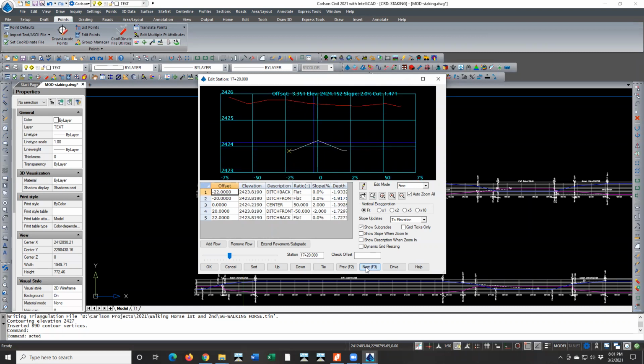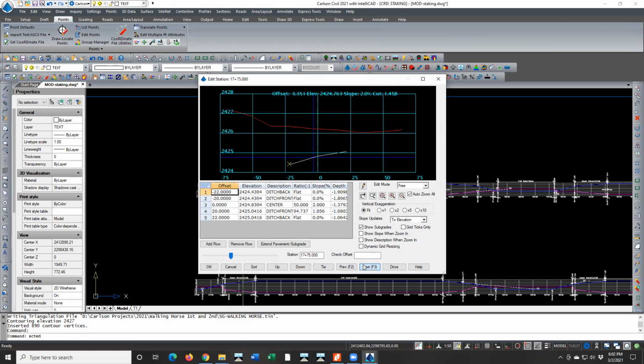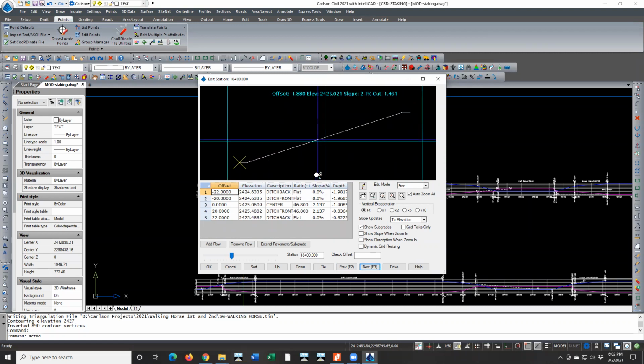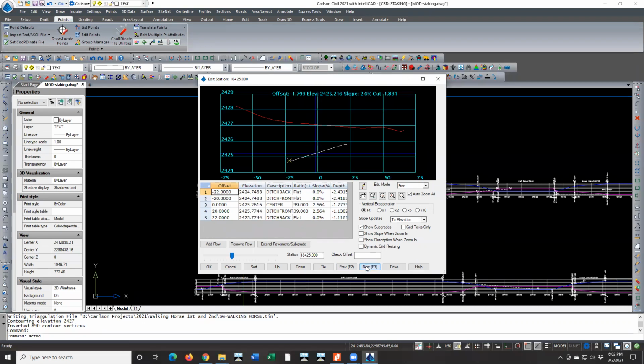That looks better. And everything's holding. So I'm wondering how the super elevation diagram will look now. So now see, it's all holding that 2%. Now, this is now in full elevation. Is it? No, maybe not quite. Should be like 19 plus 60 or something. Yeah, there it is. Now I'm in full super.